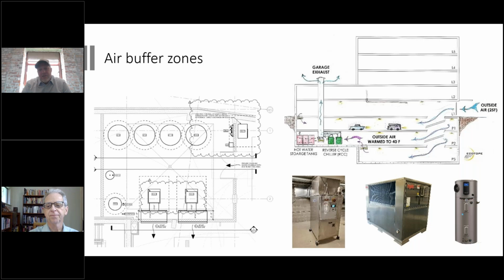And then if you can locate it near the garage exhaust, that's a great place to put it, because we can tie into the garage exhaust on a temperature and sort of flush the garages out with that exhaust. So it's a great little measure to activate the garage when the temps drop too low.